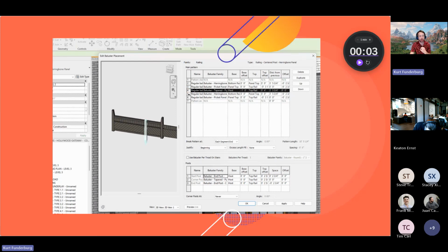And to Keaton, to your point, this is where I have a left and a right here. So I have a left chevron, like a vertical diagonal up, and then I have a diagonal down. Those are just set up with pre-baked fill patterns to have those lines. And then I can just change it to be like, these are this way, or if I wanted to rotate them I could send them outward and we could go that path. So again, it's allowing us to iterate really quickly without having to spend a bunch of time individually drawing railings or changing railings and stuff like that. Any questions?